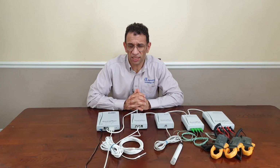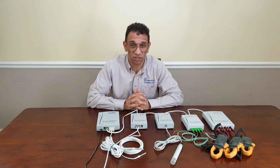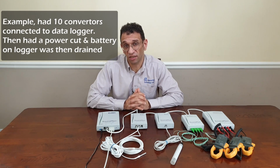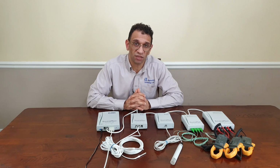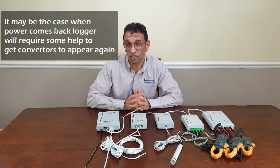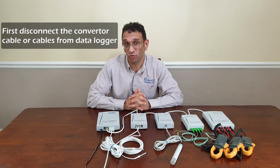So I've rearranged the setup to connect the converters to one network port on the data logger to demonstrate this next point. However, if you've got converters connected to both network ports, this will still apply. So say for example, we had 10 converters connected to the data logger, and then we had a power cut, and the battery on the data logger was drained. It may be the case that when the power comes back, the data logger will require some help to get the converters to appear again. So what we're going to do is to disconnect the converter cable or cables from the data logger as we did before.